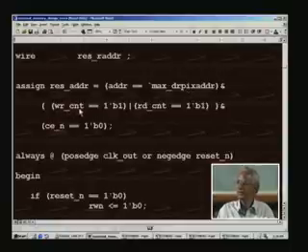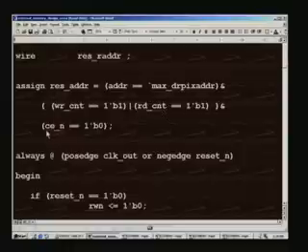if the write counter or read counter is 1, as I said before, the write counter is to scale down the speed of the memory access by 2. That is the reason why we have a 1 bit counter, separate counters for write as well as read, and whether this counter is 1 or this counter is 1, it will go from 0 to 1, it starts with a 0. So, we take every alternate clock only to process, and together with this we also need the chip enable, and only when it is enabled do we reset the address.